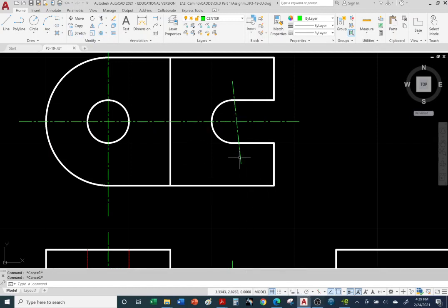Okay, so I'm going to use the grip. To try and make it vertical, I'm going to have to recreate it. Let me go ortho. So I'm having trouble recreating the vertical line. Okay, so I'll just have to recreate it over again. Hit escape. I can delete this. I'll just recreate it. If you have trouble like I just did, just start over, right? Recreate it again. So now I do have ortho on, so it's not going to create a crooked line. Okay, hit escape.